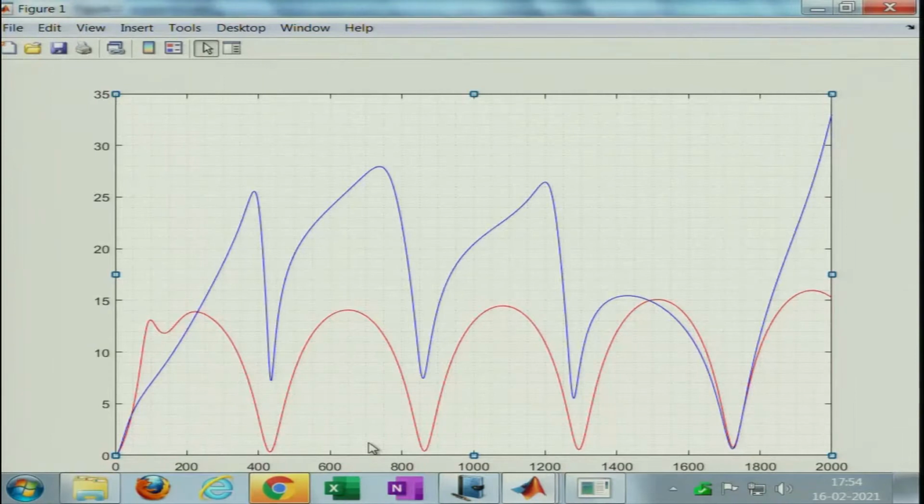So, basically the point I am trying to make is that the mean flow definitely reduces the attenuation peaks that are present, but it still tends to produce increased attenuation at the frequency range where normally a trough would occur. So, what I was saying is that the mean flow will have only a small effect on the end correction, but in presence of mean flow it is a bit difficult to tune the performance, at least in the context of one dimensional analysis.